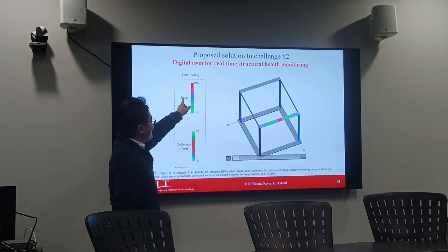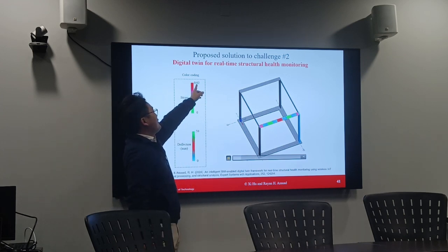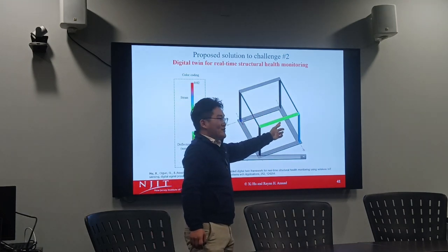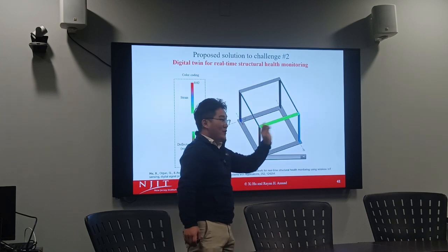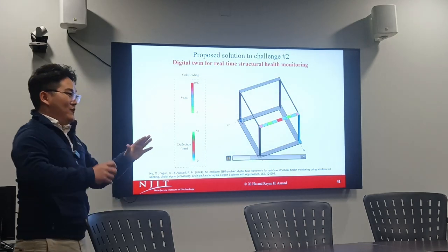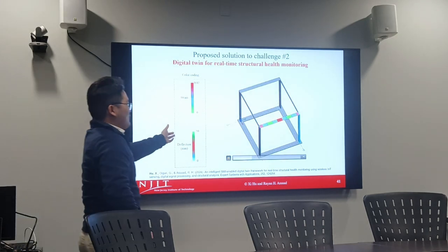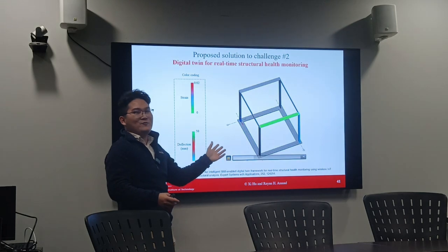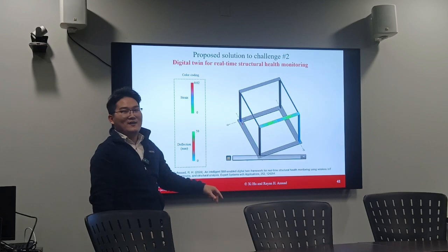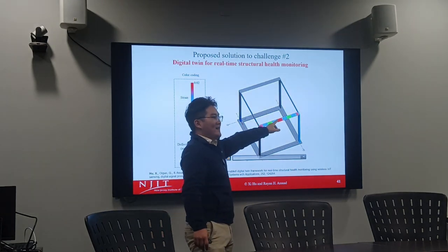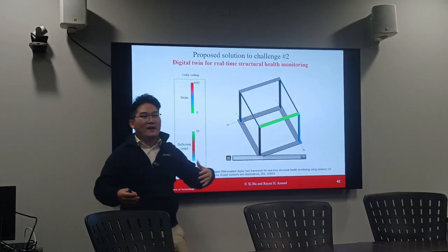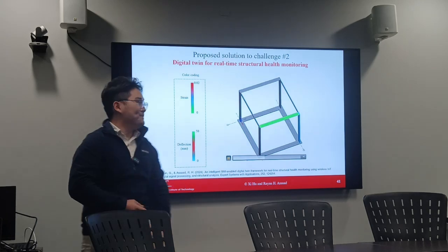You can see here, this is the strain value, and of course the maximum is 0.02. When you apply a load, you will see the strain at different locations, based on only one sensor measurement. Of course, in the actual world, the strain won't disappear so quickly, because we just did some experiments to test the entire system and make sure it works. If a constant load is applied there, the color will stay for a while. If a bigger load is applied, you will see a bigger strain.